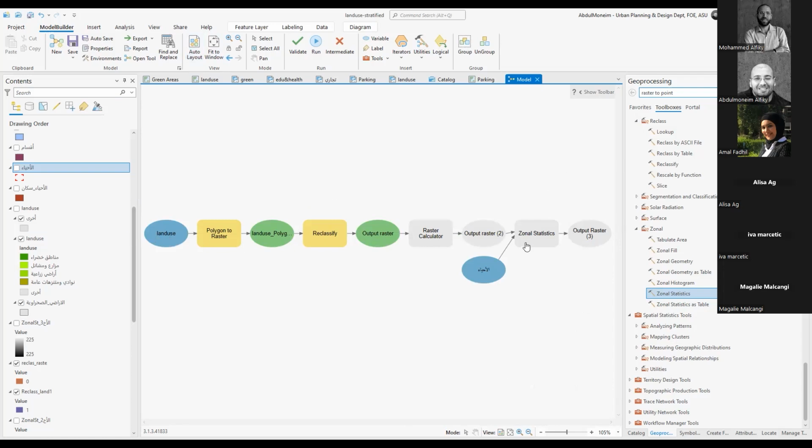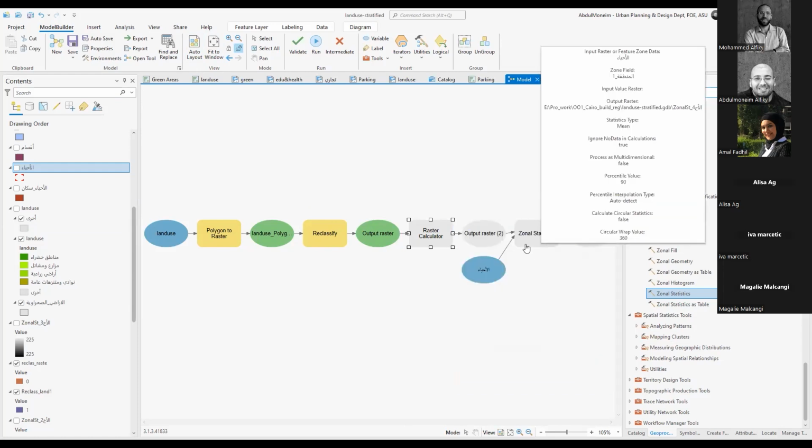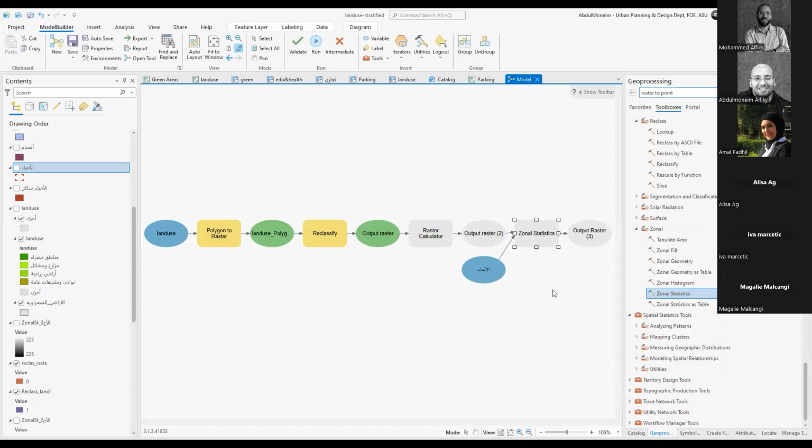So basically, this is the function. The ones that you see having color, not grayed out like this, mean that the parameters for running are already online. Those still miss some parameters, so I can click on them and check what is missing. This one, for example, still needs the equation, so I can enter the equation. Once I enter it, the output here will also have a color, and I can also choose some options. And once I'm done with that, I can simply say run the model.